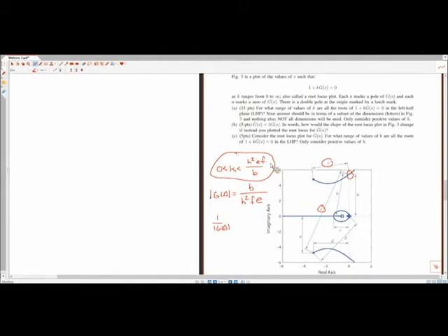This is mapping back to some of the homework problems that we did associated with lecture 2, which would have been homework 1, right? So I hope it's all coming together here in terms of all these terms. But you can look at a root locus plot and actually just draw out vectors. You don't have to have any numbers. If you had a ruler that was pretty accurate and a graph drawn to scale, you can get this purely from the geometry of the system.